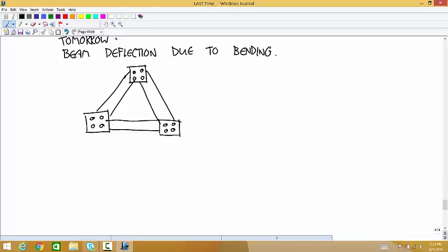And obviously, those act like weld joints. Those can apply couples in addition to forces. So they fundamentally behave differently than pin joints do. With pin joints there, it's a statically determinate system. You can use statics to solve for it. Like this, it's really statically indeterminate.